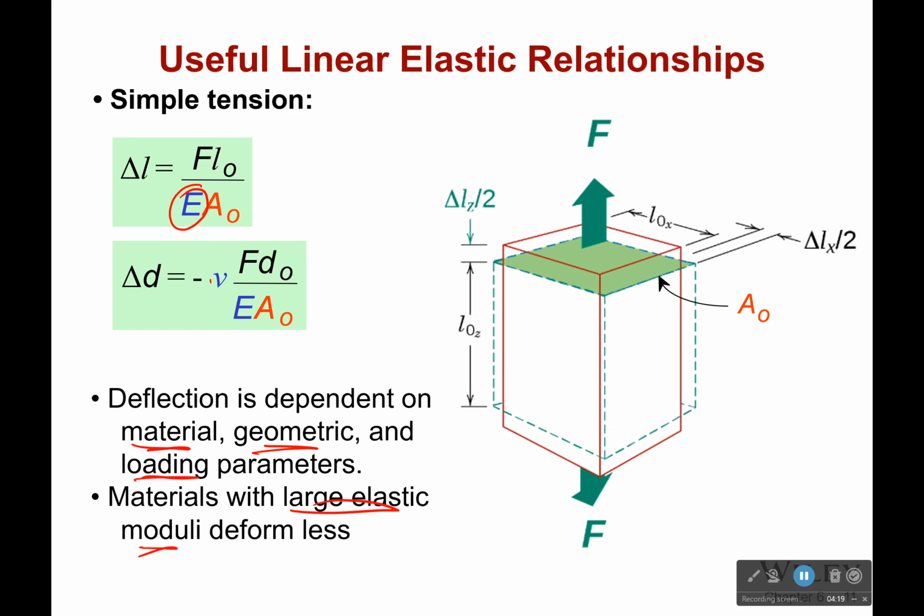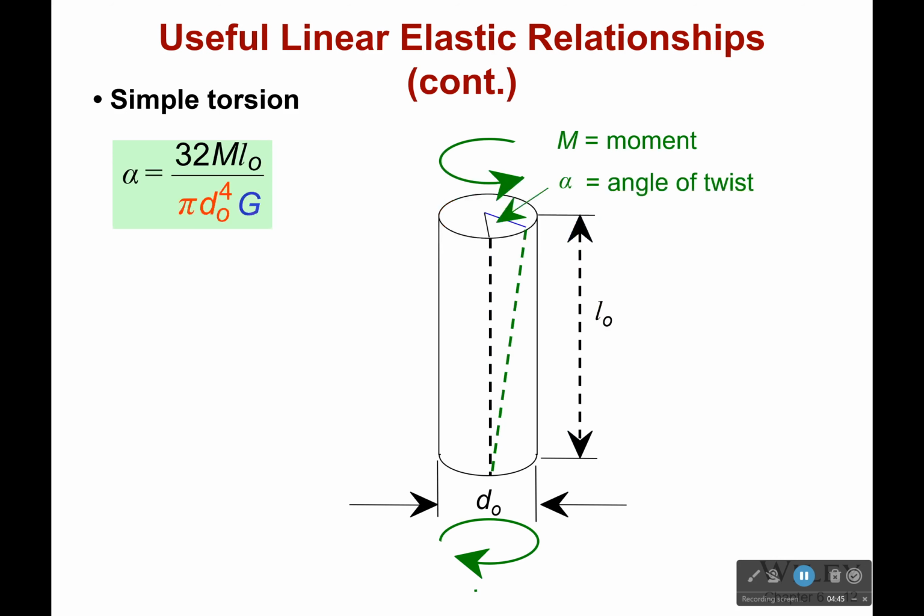It's not the case. Because remember, that's coming from that little curve. Stress is equal to modulus of elasticity times strain. And the steeper this is, the less you deform under stress. And the slope of this curve is actually equal to E. So that's where we get it from. That slope right there, that is the modulus of elasticity. And the steeper it is, the less you deform under stress. So it's actually less elastic. And that's kind of strange.